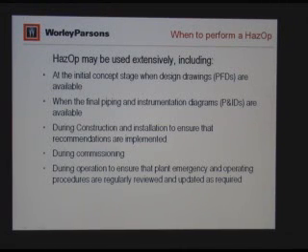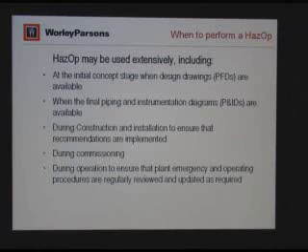So now we're going to talk about when is a good time to perform a HAZOP. HAZOP can be applied at the initial conceptual design stage when we only have the PFDs. But at this stage, what-if is another good effort to do as well.